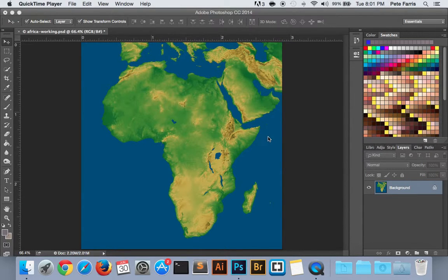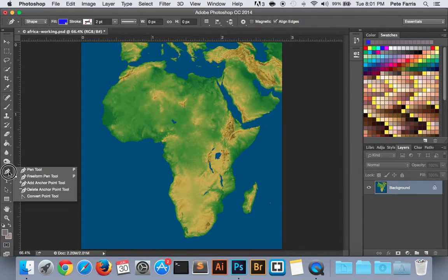Welcome back. In this video, we are going to continue our work in the Africa Wildlife Project. Now, with your project open, your AfricaWorking.psd open, go to your Tools palette and select the Freeform Pen tool. Now, first off, find your pen tool, which will be right under this little icon that looks like a hand, and right above the T icon for text.